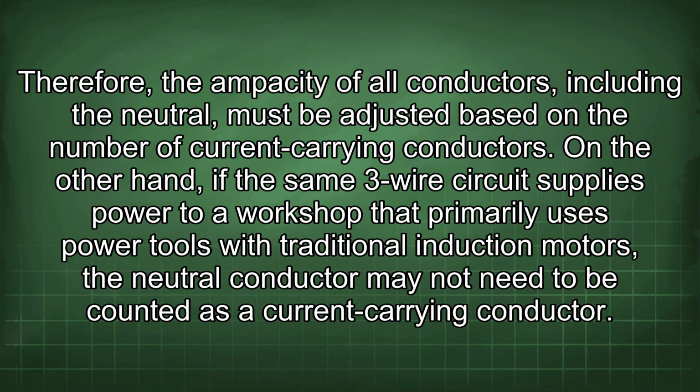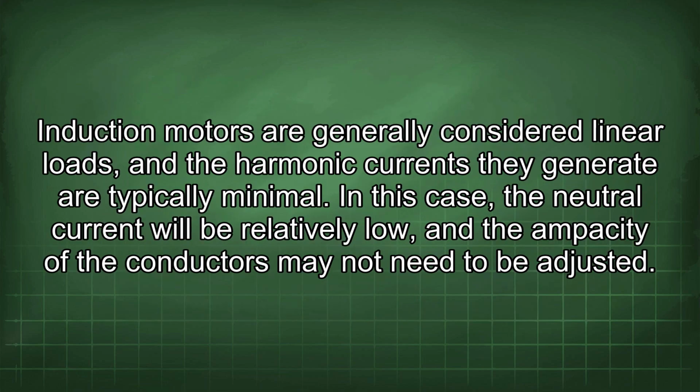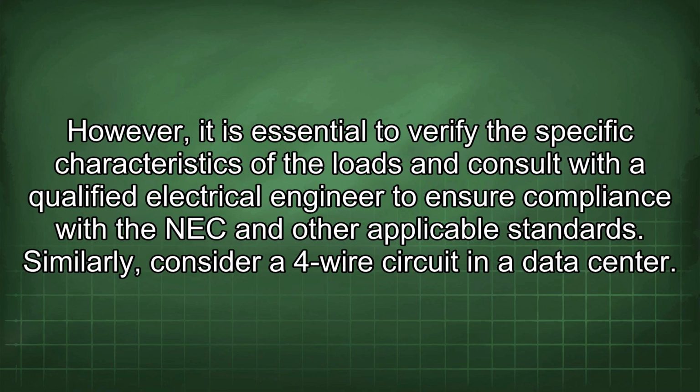On the other hand, if the same 3-wire circuit supplies power to a workshop that primarily uses power tools with traditional induction motors, the neutral conductor may not need to be counted as a current carrying conductor. Induction motors are generally considered linear loads, and the harmonic currents they generate are typically minimal. In this case, the neutral current will be relatively low, and the ampacity of the conductors may not need to be adjusted. However, it is essential to verify the specific characteristics of the loads and consult with a qualified electrical engineer to ensure compliance with the NEC and other applicable standards.